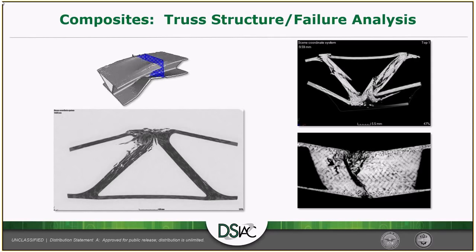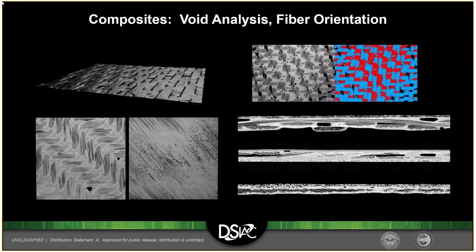You can actually go in and count those plies and feed that back into your model for validation and verification. The only other way you could do this, without using CT or some kind of ultrasonic testing, would be to physically cross-section this, at which point you could be disrupting the as-failed state, is what I like to call it. So this is just a snapshot in time of what it looked like after the test. And you can always go back to the data and look at different areas. So it's a really nice tool for preserving that as-failed state.